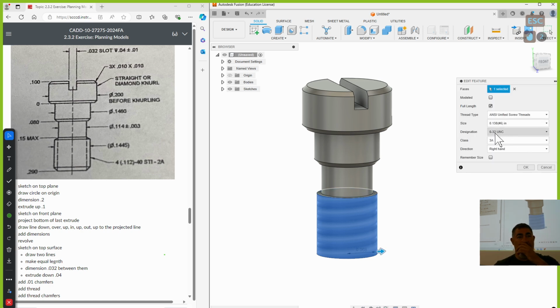So it's 6-32. An easy way to estimate your chamfer: what is the second number in the thread, that 32? What does that mean? Threads per inch. So what's the distance between each thread? Pitch. 1/32 of an inch. 1/32, the inverse of that. Not the height of the thread. And then, so that's the straight